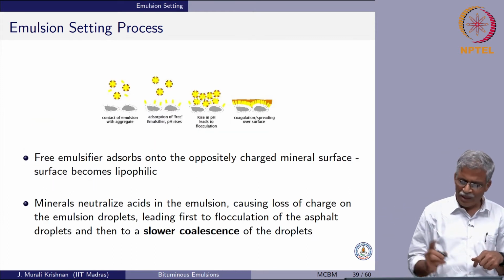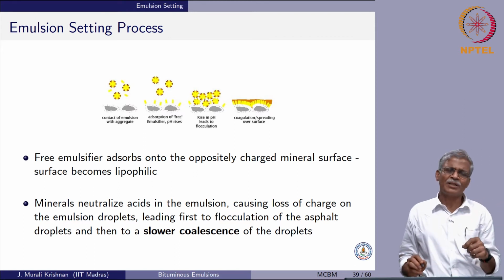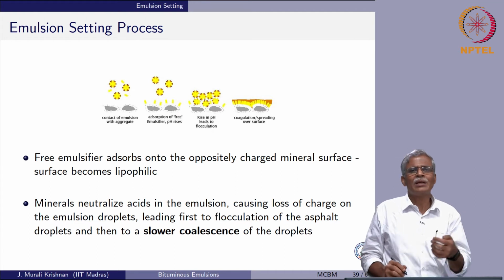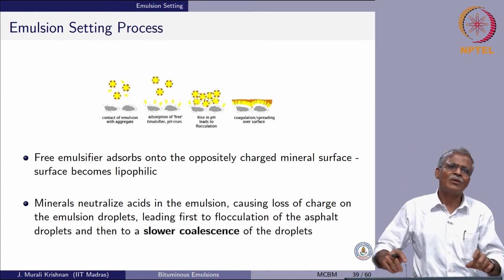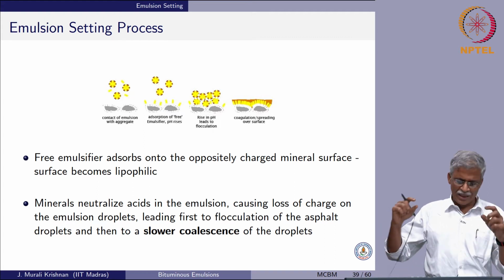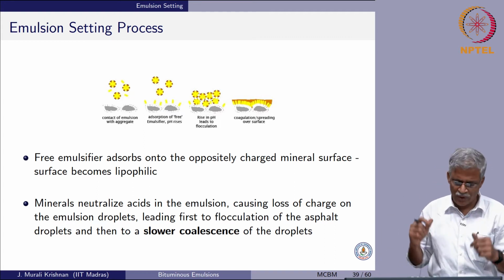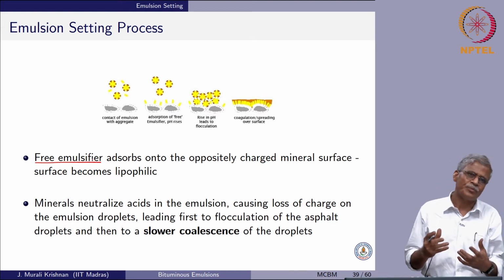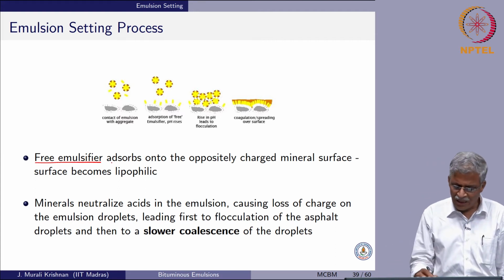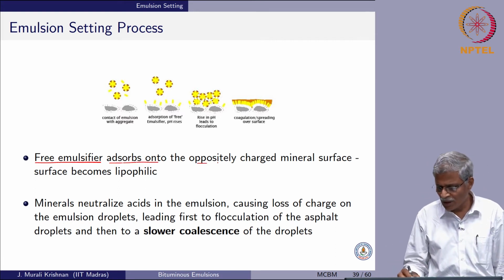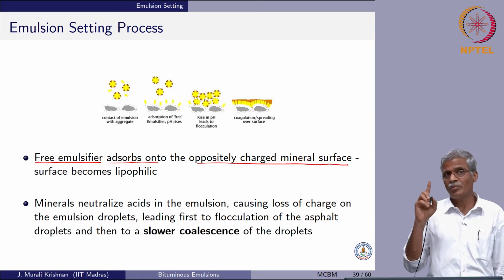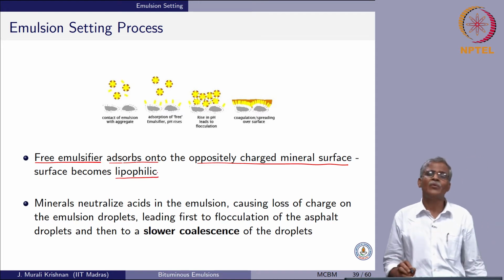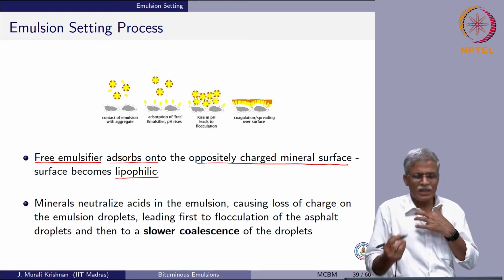So, let us look at each of these in a stepwise fashion. Since this is very important, and since you may or may not have access to the study material related to this, I have just put these items in bullet points so that you can go through this and understand how it works. Now, this free emulsifier that you have in your system gets adsorbed onto the oppositely charged mineral surface. Please remember that, oppositely charged, and this becomes lipophilic, and we have discussed what is lipophilic in the earlier slide.